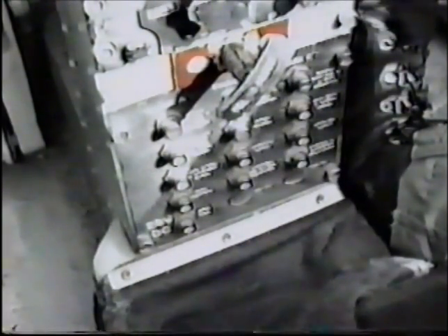Once again, check the circuit breakers to ensure none popped during engine start. If you're dual, confirm this with the other cockpit. Press the anti-G-suit test button to ensure your G-suit inflates properly. Place the yaw damper switch on. Since we don't have Block 20 aircraft, disregard Step 5.